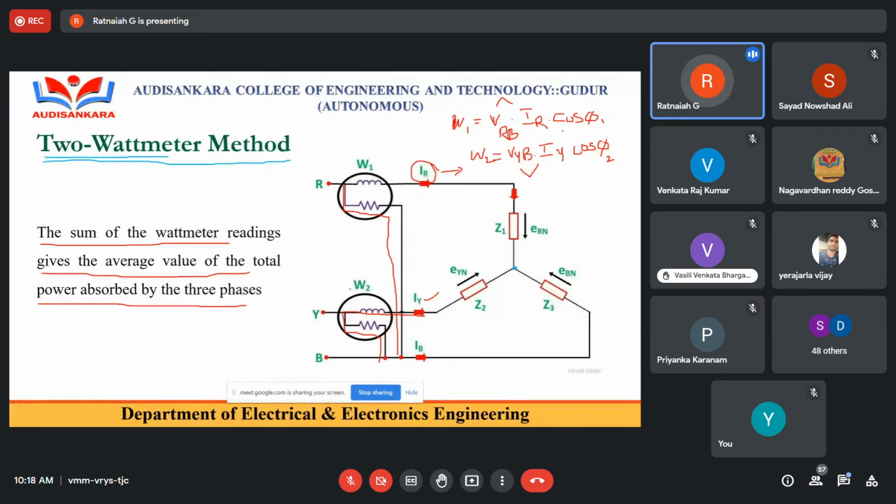So if you make these calculations for W1 and W2, what is the total power absorbed by the load? There you can write P is equal to W1 plus W2. Generally in any three-phase system, the total power absorption is always equal to root 3 times VL IL cos phi. This is a general expression.